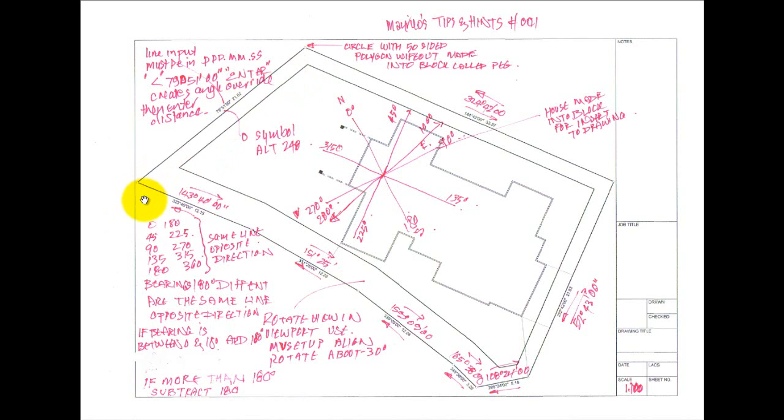The thing is though, that if you put the little circle in, you get the lines underneath, and you don't want to trim the lines because that'll trim their length. So you want it so when you click on the line they stay the same. So what we do there is we just put what we call a wipeout under the circle. Now to create a wipeout, you first of all have to create a 50 sided polygon.